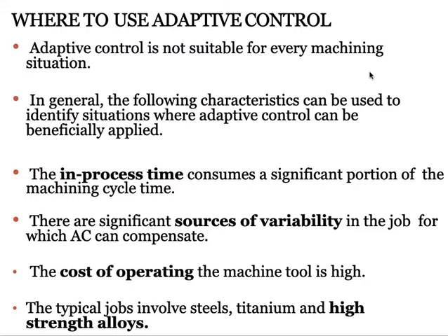If these non-productive elements are reduced relative to total production time, large proportions of the time can be spent actually machining the workpiece. Although NC or CNC has a significant effect on the reduction of the non-productive time, it can do relatively little to decrease the in-process time as compared to the conventional machine tool.